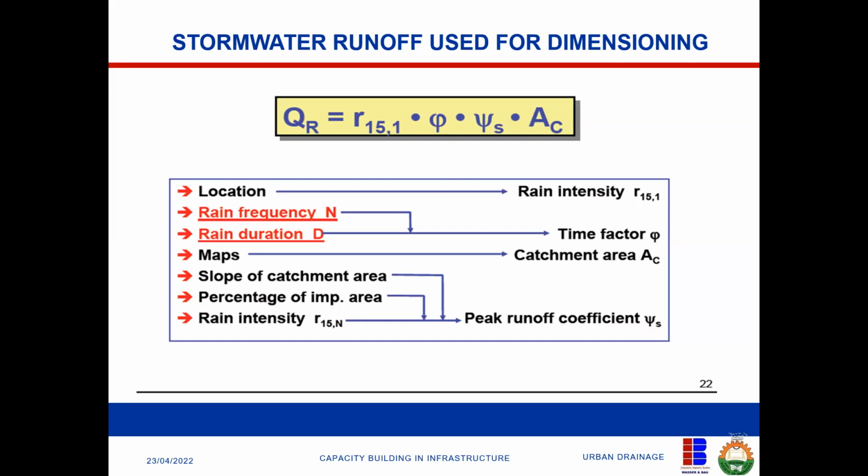When I say, when you are reading, it's a function of D and N. So if you are reading it off, you read it from 15 minutes, and then also from the return period, which is 1. So this one, 15:1, is like a guide. When you go to the charts, you look for where there is 15, just like we did last week in our cost engineering, where we were using the interest table. So when you are reading from the chart, you go for the 15 minutes, then you go for the one that has a frequency of 1.